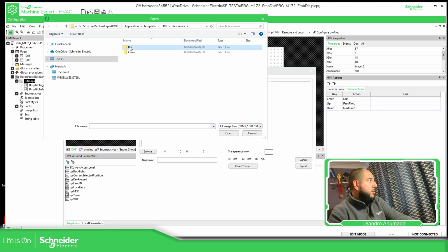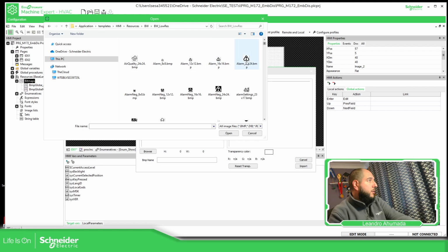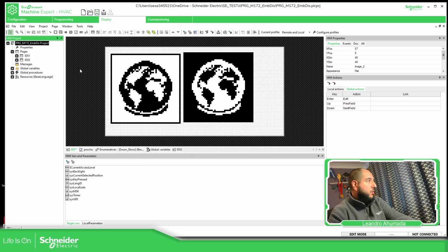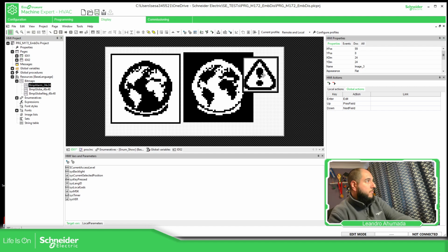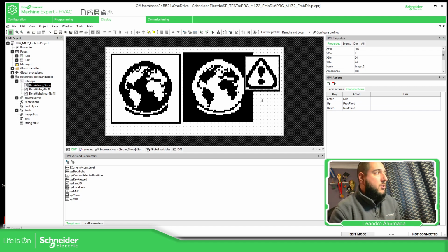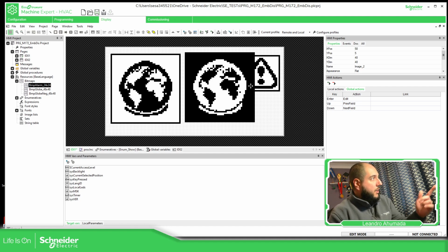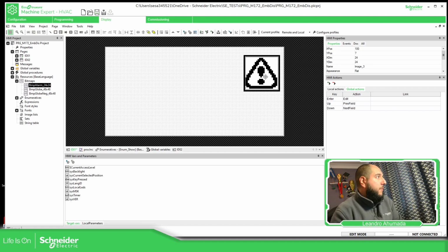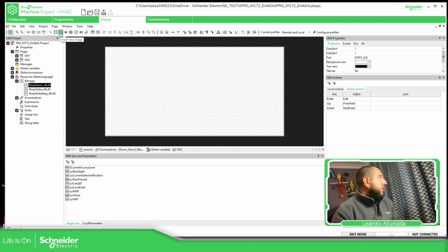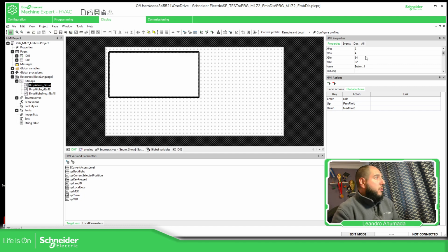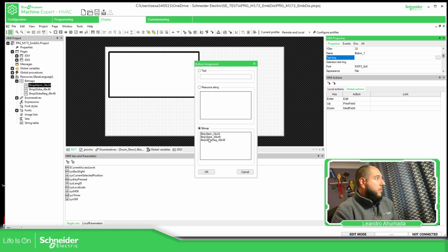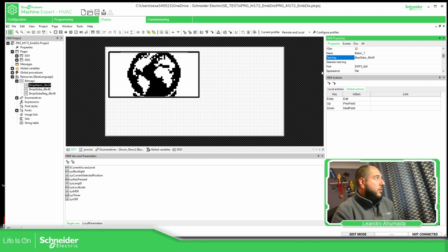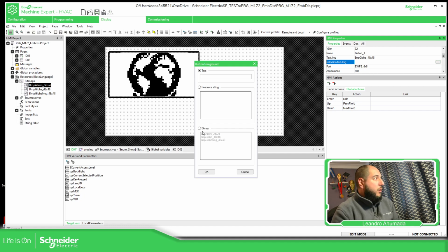And then to just import the one that you need, let's go for the lower one. See this alarm. Import, just drag and drop it. Okay, so you need to be creative with the images that you're going to use. Now, the idea of selecting this is because we have the possibility to use, for example, the buttons here, and we have the possibility of text or images with selection or not. So here, bitmap, this one is when it's not selected, and this one is when it's selected.